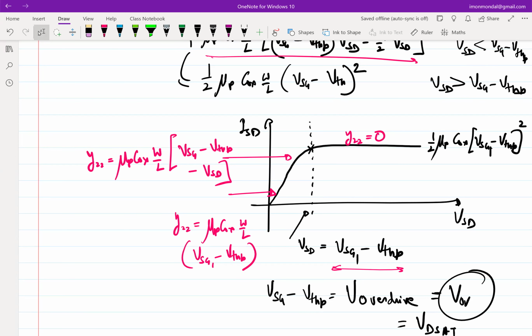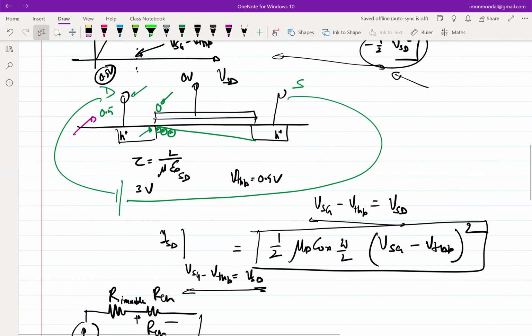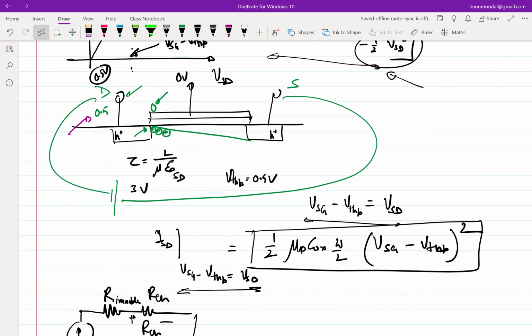Okay. Another important nomenclature that you might find when you flip through textbooks is this critical voltage or this phenomenon where the current gets saturated. I haven't yet named that region of operation. Whenever this charge profile gets pinned to this triangular profile, essentially that time we call it the pinch off has happened.